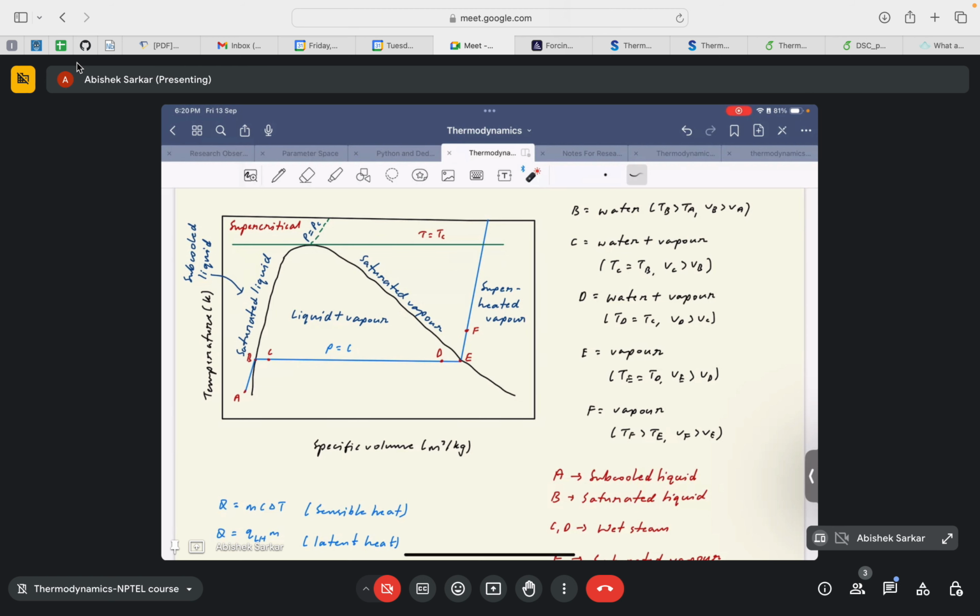After some point of time, when the heat is being continuously applied, the liquid phase of water gets converted to the vapor state, so the quantity of vapor in the liquid vapor mixture increases, basically the mass fraction increases. So the amount of vapor in the liquid vapor mixture is higher in the later stage of heating during the phase change, right? So the vapor content at point D would be higher than the vapor content at point C,